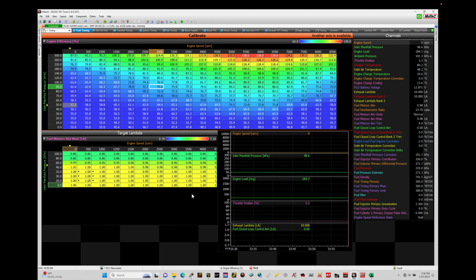Now the Motec, because it's based on a volumetric efficiency style strategy, we tell the Motec what size injector we're controlling, and then it knows, based on the desired fuel mass through the air and fuel model, what we want to inject into the engine. It can then just take a look at both injector flows and figure out what pulse width each injector needs to run at if it knows what injectors it's controlling for both primary and secondary. It's actually really simple to configure and set up.